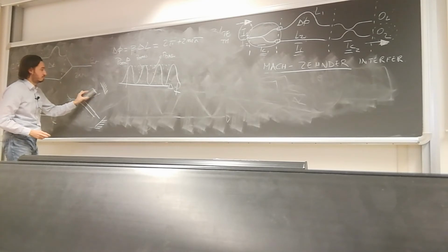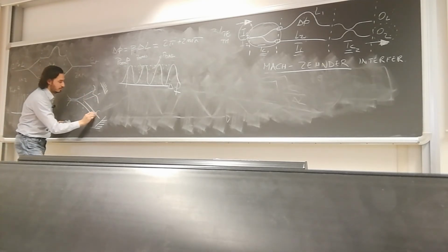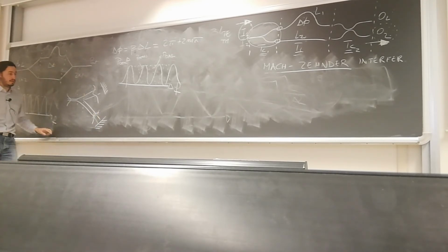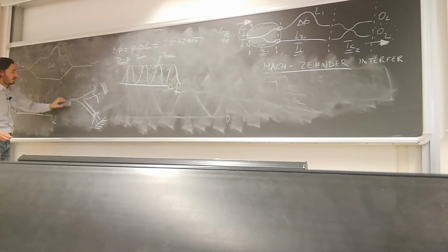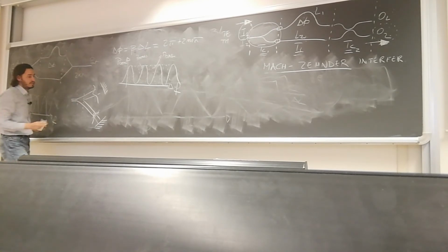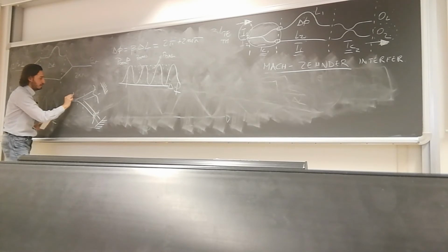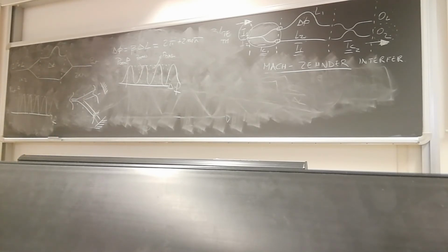These two guys go back and assume that everything is still in phase. And if I enter from the two-port side in the Y branch with equal phase, they add in phase and they build again my fundamental mode. Okay?